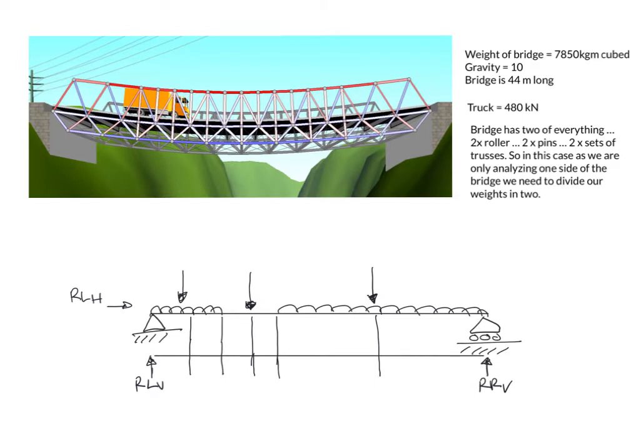So here we go. We have our FBD, free body diagram drawn, and that has been taken from the space diagram which is up here. Remembering that the difference between the space diagram and the free body: the space diagram shows the situation as it actually is in real life. Free body, we get rid of all the junk around it, so it's broken down into a simpler way that we can understand that will help us do the equations.